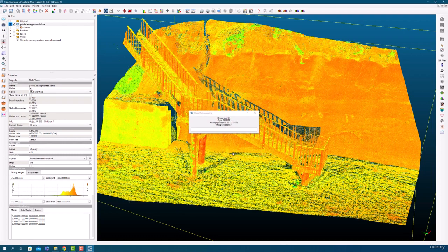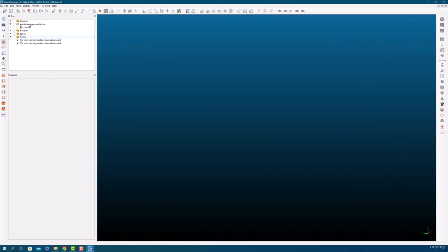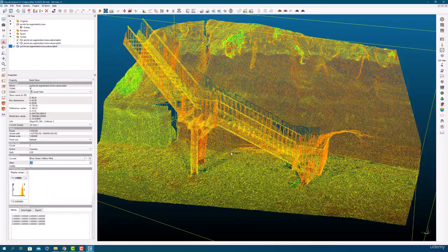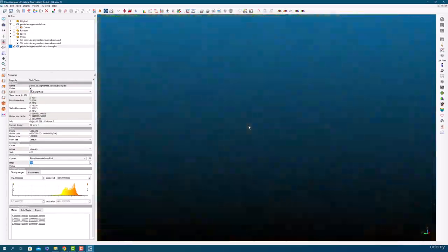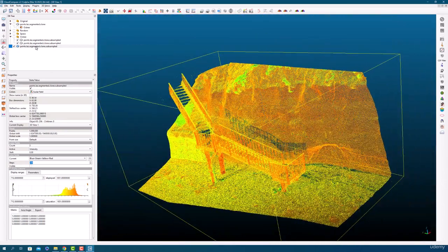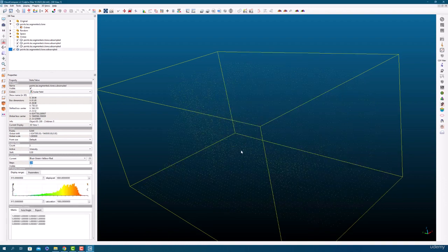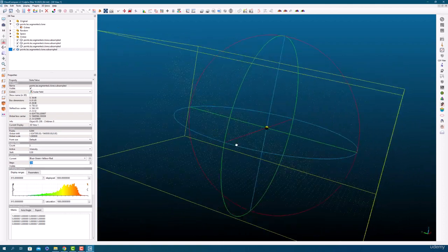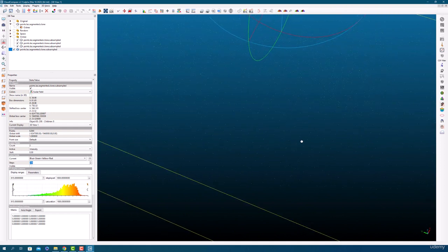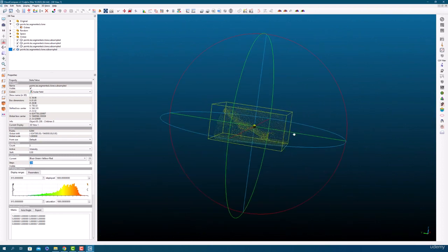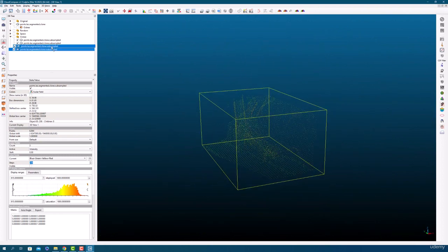By changing the parameters, you can adjust the sampling results to get the perfect subsampled point cloud that you are looking for. The octree subsampling method can be useful in situations where you want to simplify a point cloud while preserving its overall structure. Just like the previous two subsampling methods, you can also use a scalar field to modulate the subdivision level with the scalar values in the octree subsampling mode.